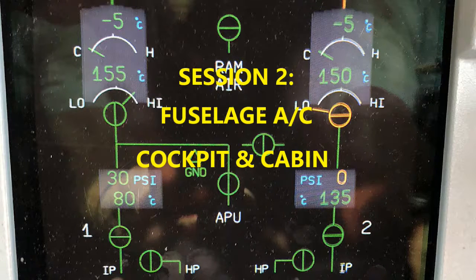You do have faults and indications regarding the pressurization, obviously. So, you've got the controller power-up test. Like I mentioned before with the zone controller, you've got a power-up test. Well, you have the same thing here with the cabin pressure controllers. There's a power-up test if the aircraft is on the ground and engines are below the minimum takeoff power, and also if the power-up test is done after a cold start, okay, and a reset or a power supply interrupt. So we have kind of similar conditions as last time when we talked about the power-up test.